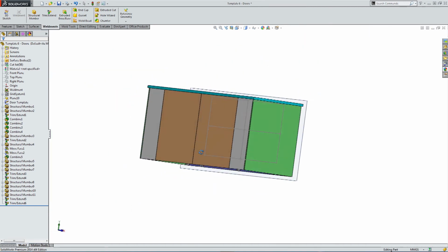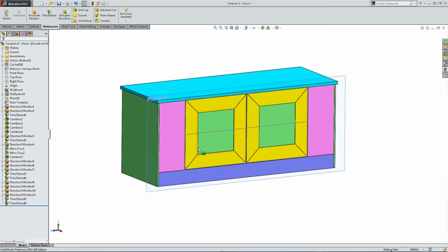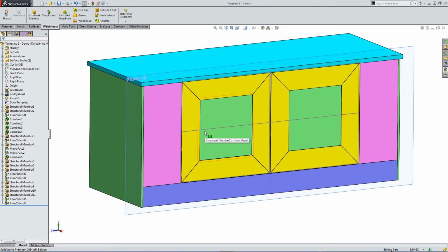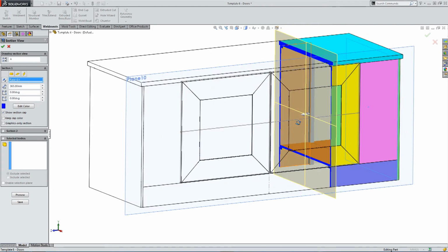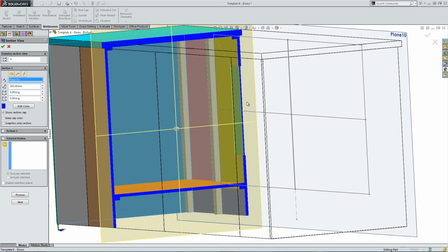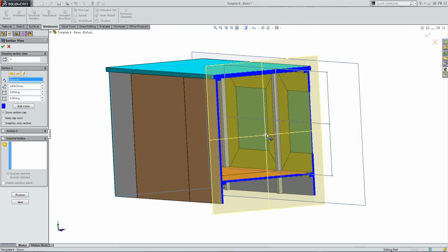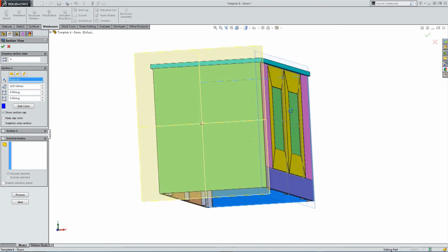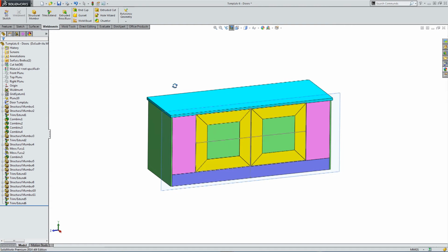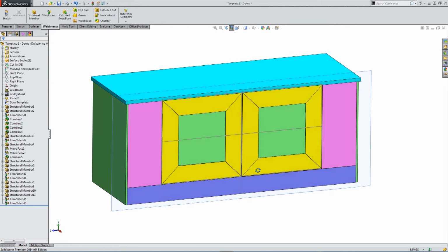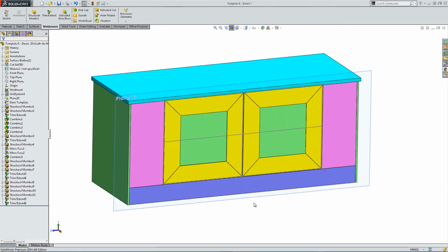So in essence, we've got everything now in terms of weldments for this assembly, or at least weldment assembly. Now the reason why we haven't built this in an assembly as opposed to as a weldment is because we can put together a cutting list. So this is a singular part which you could take that cutting list, put into a drawing, and reel off a table of parts.